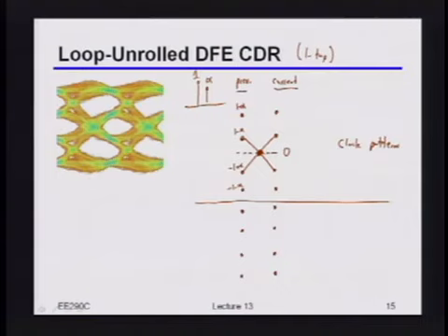What are the other, let's say, possible things that you could get in terms of having arcs from one analog point to another? And by the way, I'll give you a hint. Just start from some point and then see what would happen on the next data bit if you actually made a transition. 1 plus alpha to minus 1 plus alpha. Yeah, exactly. You could go from 1 plus alpha to minus 1 plus alpha, right?